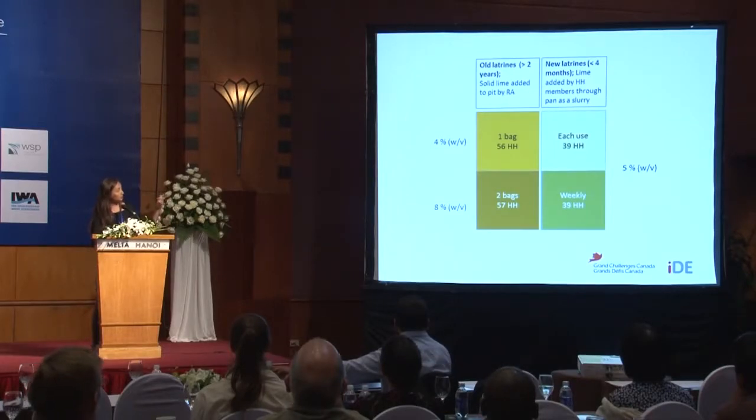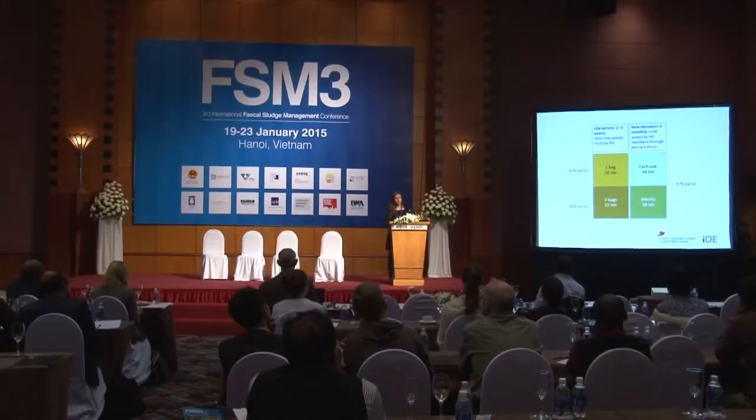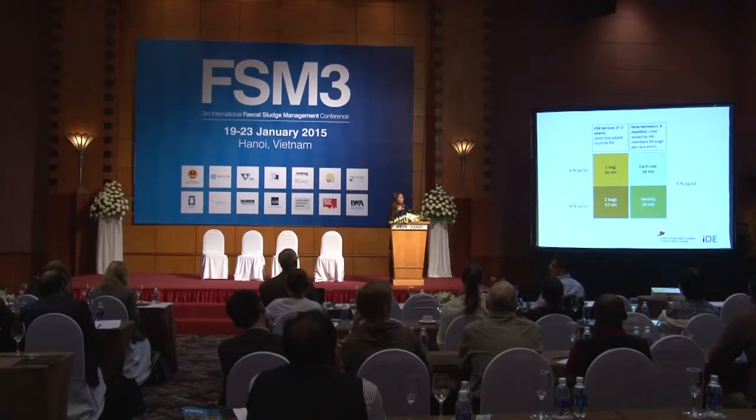39 new latrines, so these latrines were built and in use for 4 or fewer months. In those households, we had the actual household users add the lime as a slurry through the pan. Some were asked to add it at every use, and the other half were asked to add it on a weekly basis. So sort of like when you clean your toilet once a week, you would add a prescribed amount of lime. And this was at approximately 5%